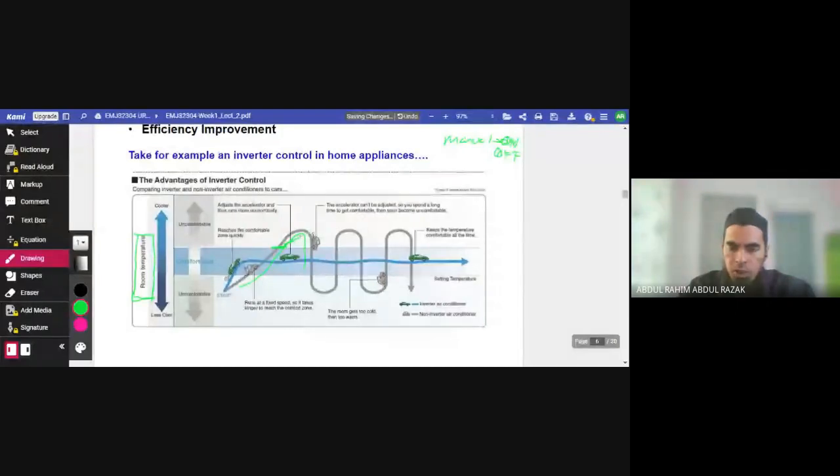Once we switch off, the compressor will stop and the temperature of the room will drop. After it reaches the lowest range, we have to switch on manually, or the sensor will detect the level and switch on. So it switches on, then off here, and on here. You can see that we have only two kinds of control, on and off.